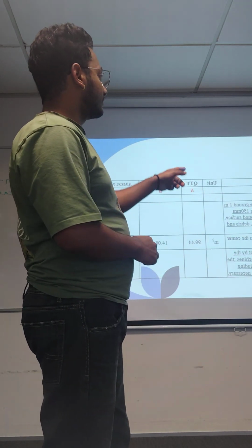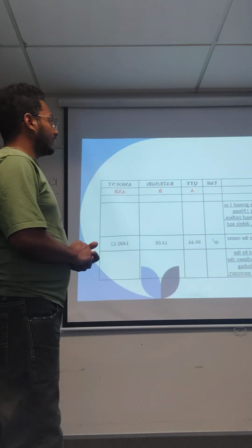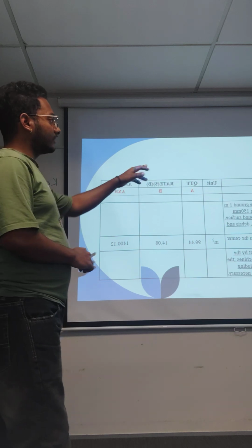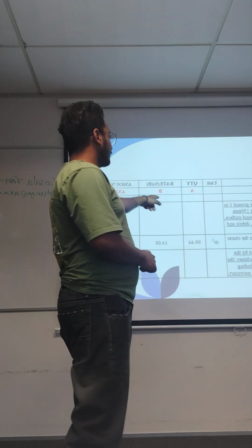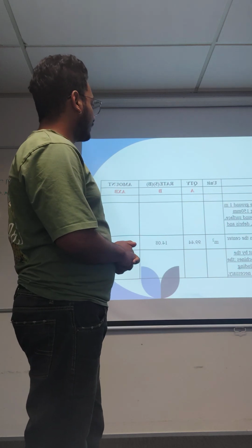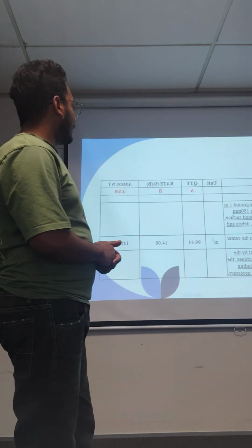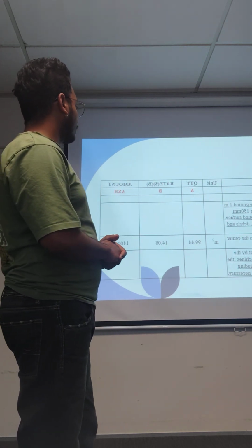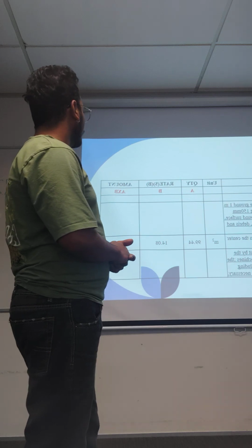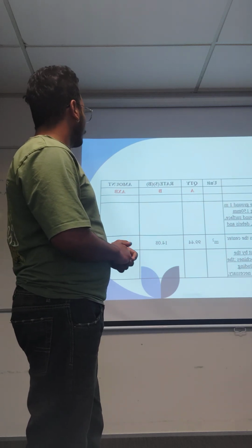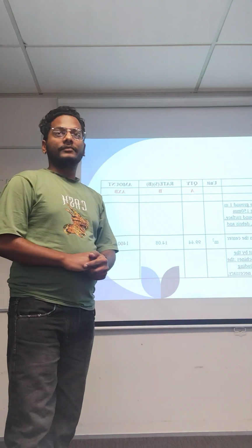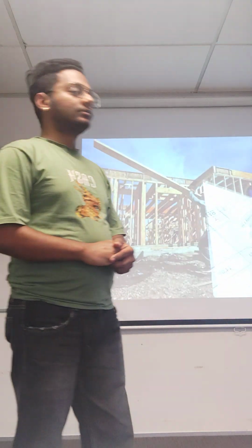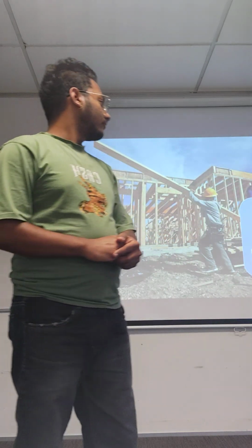As in this SOQ sheet, we need to prepare this one. The unit is square meter, the quantity is 99.44, the rate is 14.08, and the amount is 1400.12. Thank you for your attention.